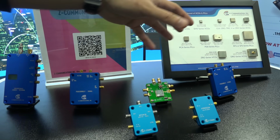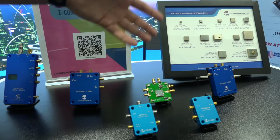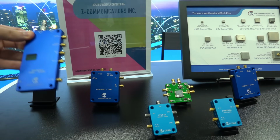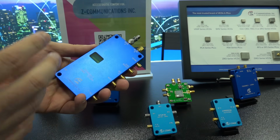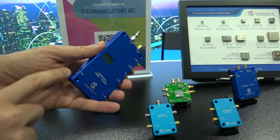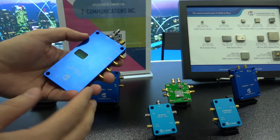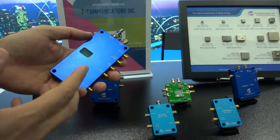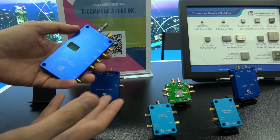Now what they've also done is that they now have a whole slew of these compact modules, LNAs, amplifiers, power amplifiers, and so on, but then they also have these kind of smart PLLs, which have a lot of really useful features. First of all, these are controlled with Bluetooth. So you can either control them with USB-C or Bluetooth, or power from USB-C. This particular model has a built-in amplifier, things like phase synchronization, lock detection, and so on, allowing you to basically set the carrier frequency from your phone, from an app, and then connect it to the system you want.